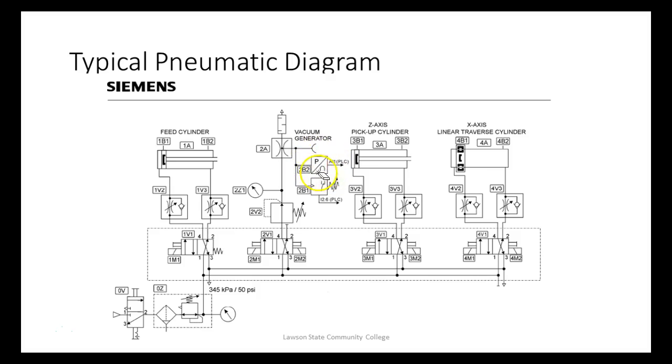This is our pressure switch right here. I'm sorry, this is our pressure switch right here. This is an analog pressure switch right here. So not only does it give us an indication of when the pressure is at a preset, this means that this one is what? Adjustable. So we can set the pressure on it. And this is a knob people can turn with their fingernails. So guess what? It's going to happen sooner or later. Somebody's going to change it, right?